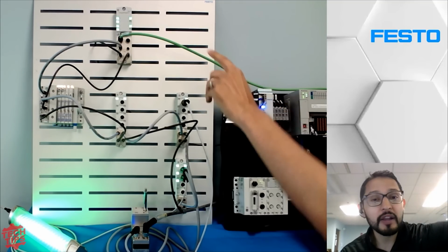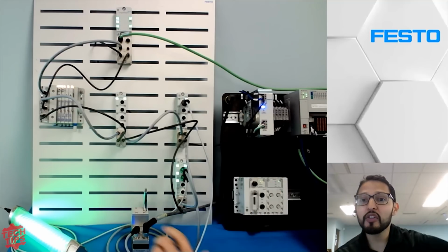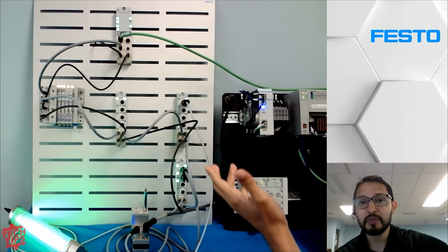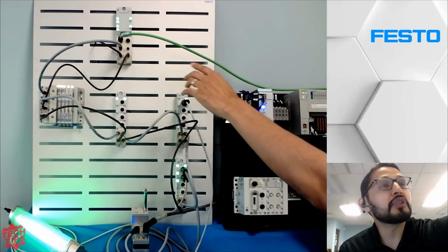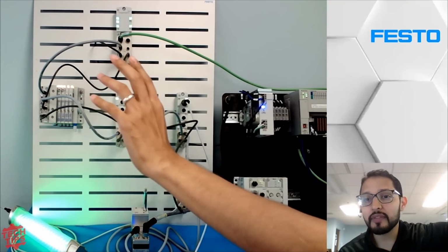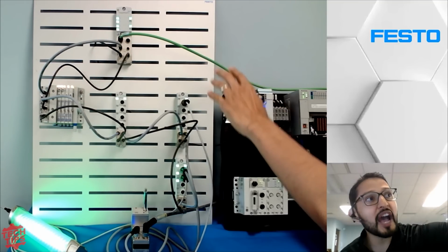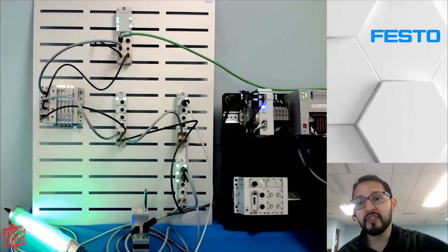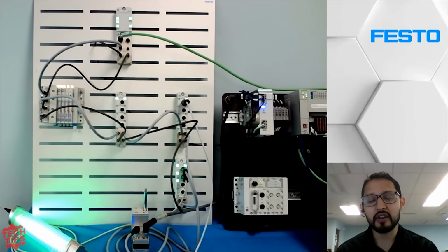address, and distributing all of my I/O across several modules. So that means that I could also have a vision system with Ethernet IP, maybe 2 servo drives, and that's about it. But I could have many I/O, including valves, with just one Ethernet IP connection. That's something you wouldn't be able to do if each of these modules were Ethernet IP themselves. This particular controller could not handle it. It just doesn't have that many.